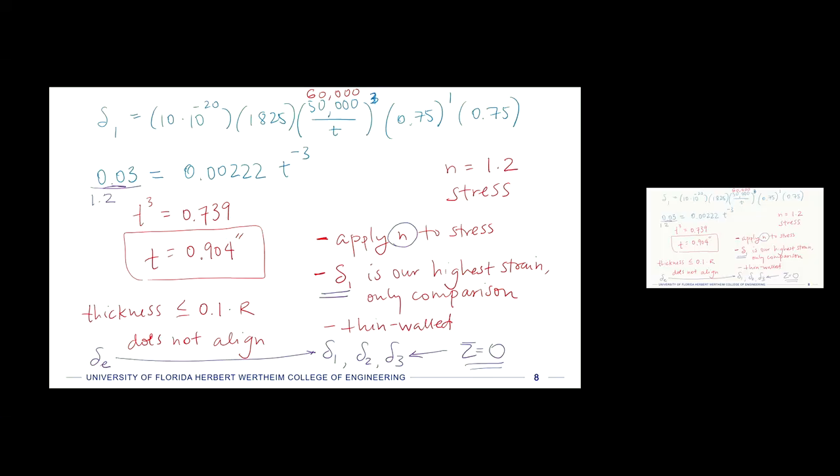And so you can do that as well, but if you now are taking into consideration 2 directions of stress, now we have 2 directions of strain, and we have to then, again, have a thicker wall. So what we really find with this problem is that no matter what our assumptions are, we can't use the expressions for a thin-walled pressure vessel.